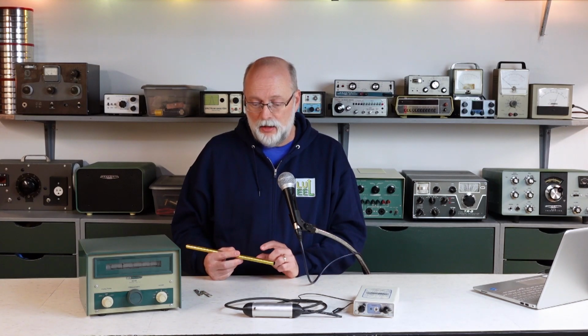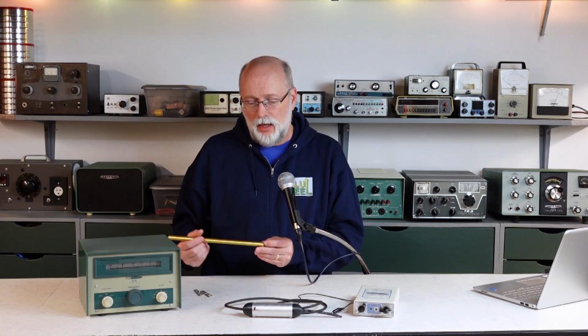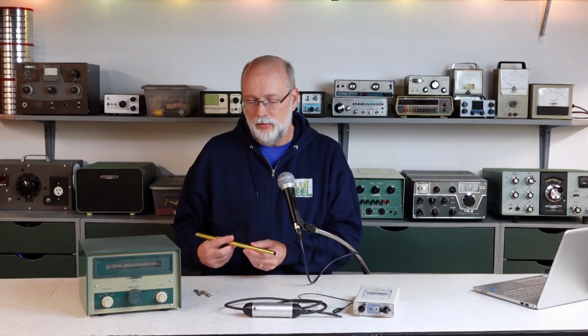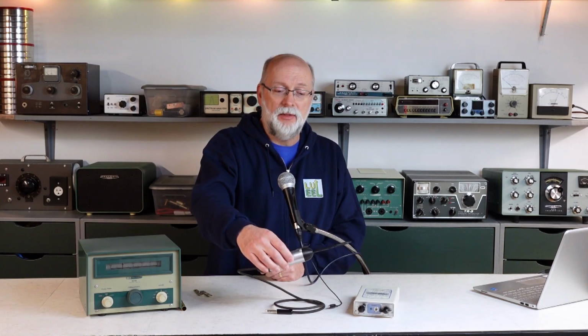They're not that complicated, and in fact, as I stand here recording the ending for this episode, I've already chosen a fabrication direction. I'm going to use a piece of 1/2-inch diameter brass tubing, cut the length for the probe body. That'll also provide some shielding for the probe circuitry, and then make some skinny circuit boards to fit right inside the tube, and design and 3D print some end caps for the terminations and the cables and the wires that come out. So it's going to look like the little brother of the Mr. Carlson Super Probe. This is my version of it that I built a few years ago. So it'll be pretty rugged.